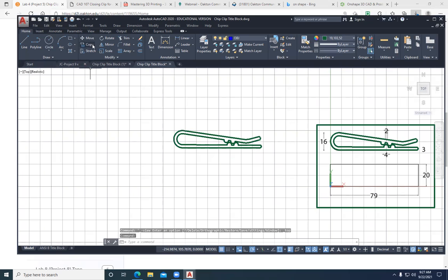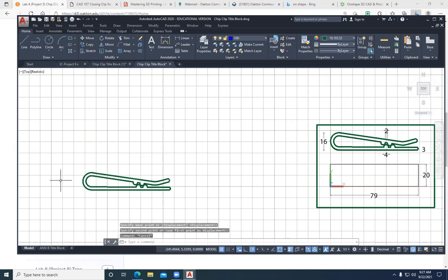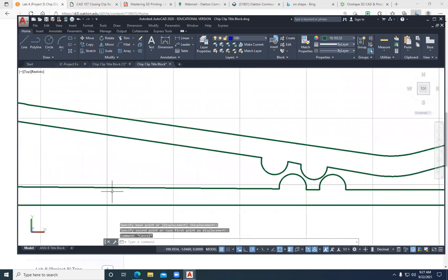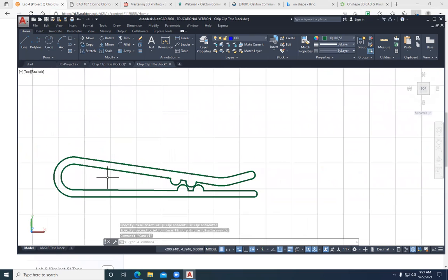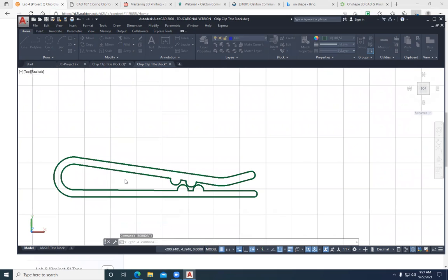Let's move it, copy it. Type in boundaries, please. Select inside edge when it comes up. So what he's going to do is create a new boundary for it. Doesn't want to do it. I'm going to say B poly. It's the same command.